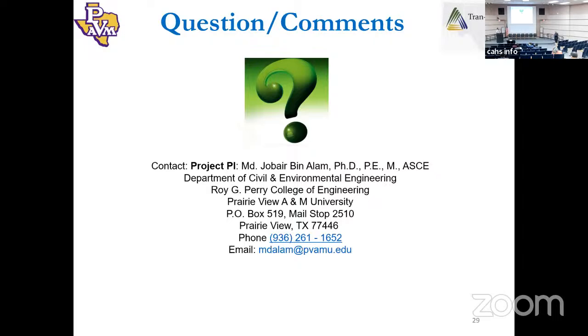Okay, it's a very good question. So if we know that the clay soil we have in our project area contains a significant amount of montmorillonite or illite or kaolinite, which are the clay minerals that cause the problem of swelling and shrinking, but if we want to remove all this soil and bring new soil, the transportation cost of the new soil and removing all this will be more than 50% of the total project cost. So even if we don't want to, we cannot do it, because the cost is very, very high to transport the new soil and remove all this problematic soil.